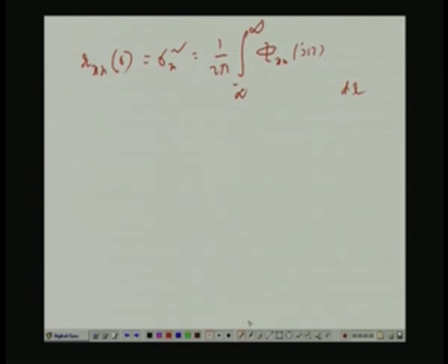So, you see this gives all the information that phi x x j omega is such a real valued function that when you integrate it over the entire frequency range, you get the average power of the signal. So, that means phi x x j omega gives you an idea of how the power is distributed along various omegas. That is what is called power spectral density.